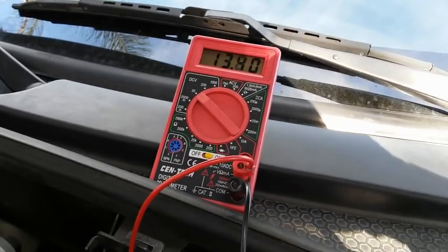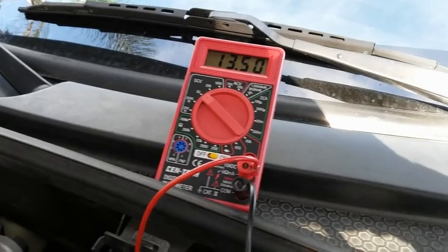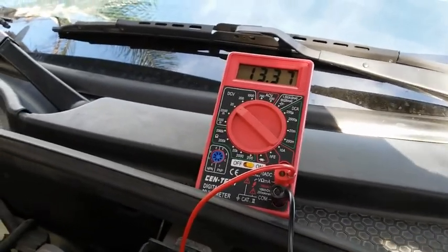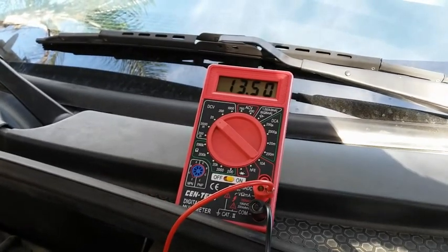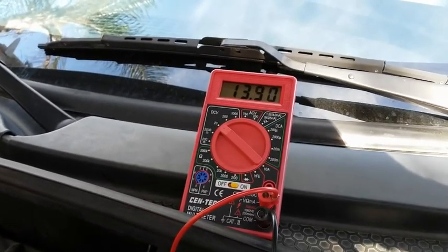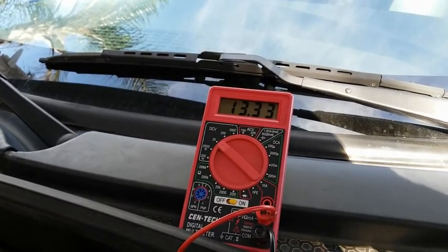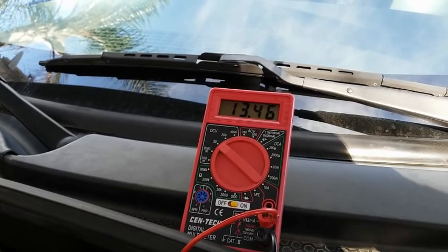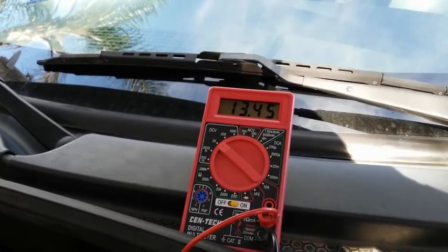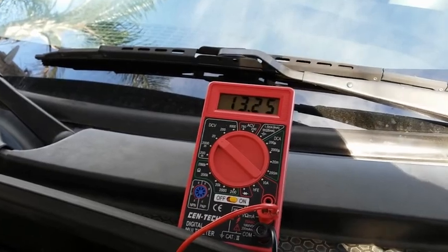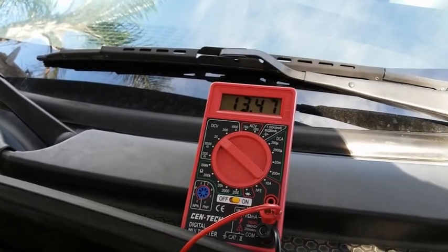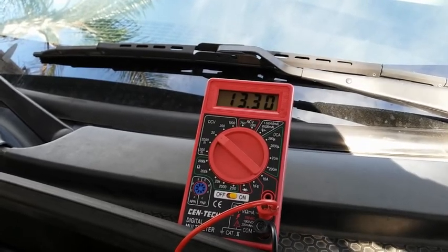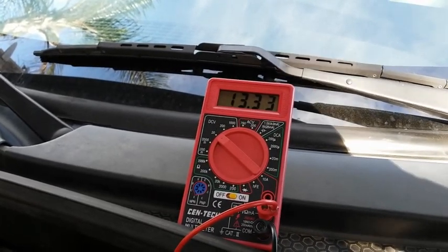Alright, so the next step, I'm going to shut the vehicle off. And remember, on these Chrysler PT Cruisers, it takes about 90 seconds for the oil to bleed off the sensor. So with the key on, engine off, our signal should remain approximately battery voltage, but after 90 seconds, the voltage should drop to approximately 0 volts. And if it doesn't, that means that we have probably created the intermittent problem. That means that the sensor contacts are stuck open.